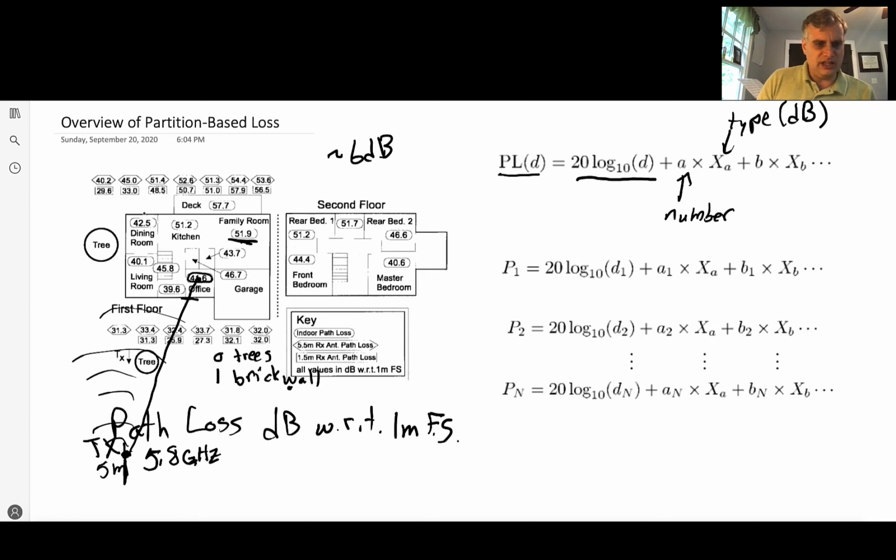And we don't go through any of the interior walls. So the loss here is due to free space, according to the model, and then some value in excess of that. So the path loss would be 1 times whatever the brick wall loss is. Brick walls are usually anywhere from 12 to 16 dB of loss. So maybe we put a 16 dB here, and then zeros for any other subsequent partitions for this particular location combo.